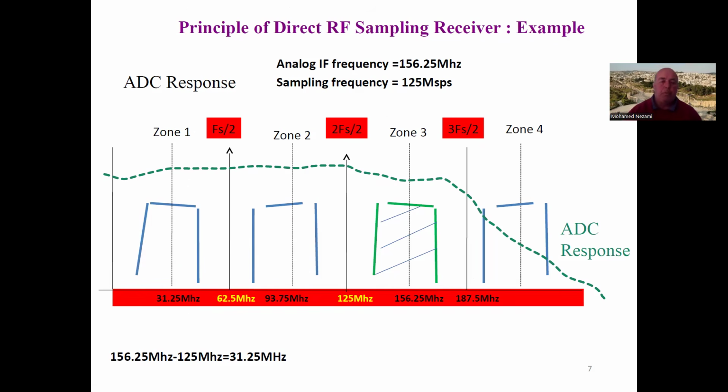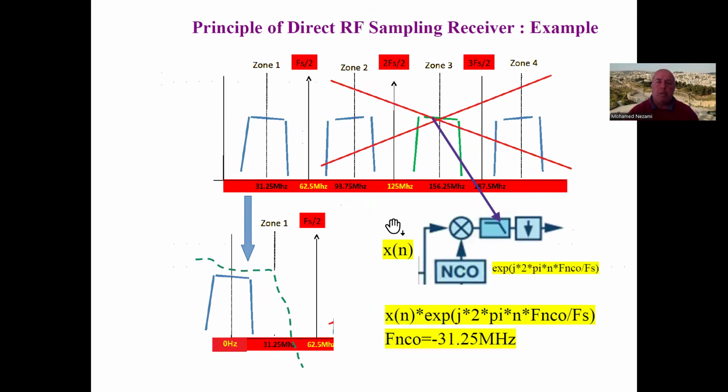And you can work out that the ratio between the sampling frequency and the center frequency is such that all you have to do is alternate the sign of the I and Q, and therefore you don't even have to do mathematical operations. That's sampling at 4 times the IF, or the IF being 1/4 of the sampling frequency, and you get that relationship.